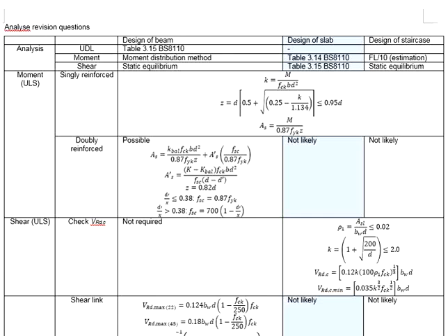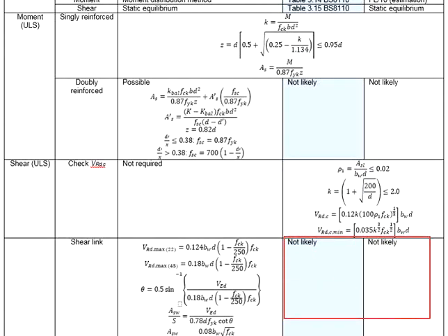And because of its relatively large cross-sectional area, the design for the moment and the shears is relatively simple, especially when dealing with the shear resistance. The concrete member itself is sufficient to carry the shear loads. That's why no shear reinforcement shall be required.